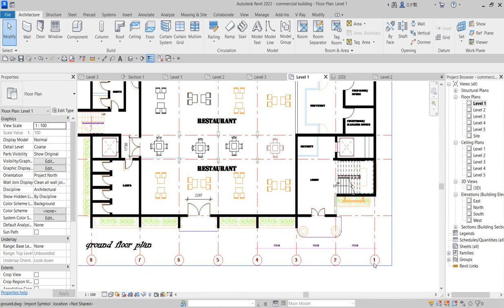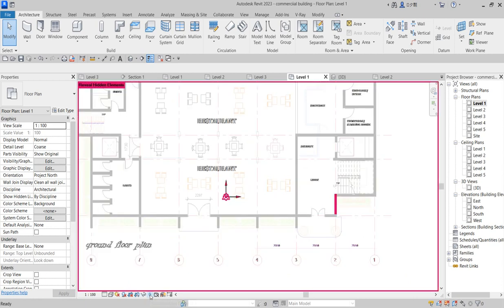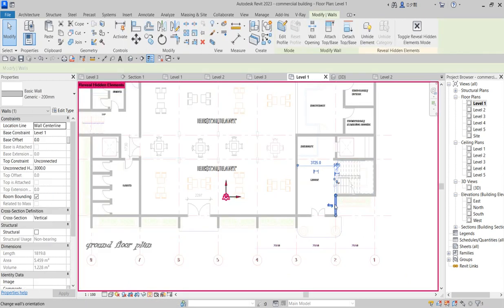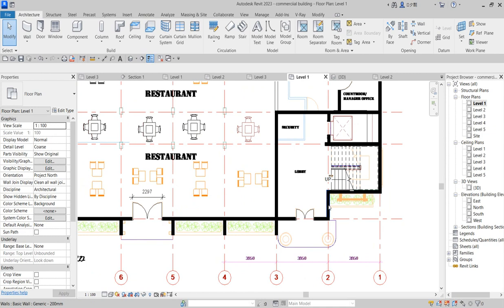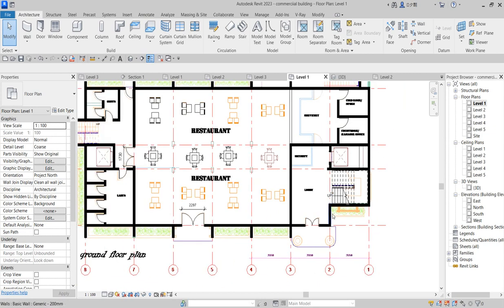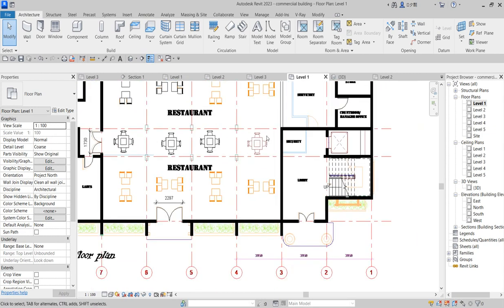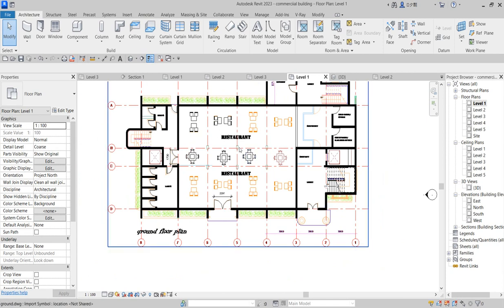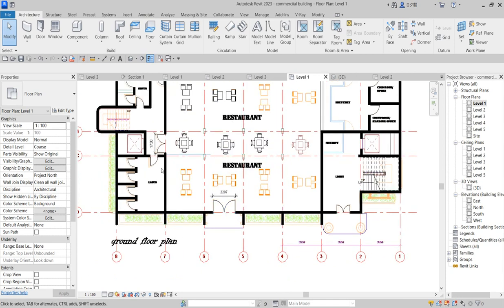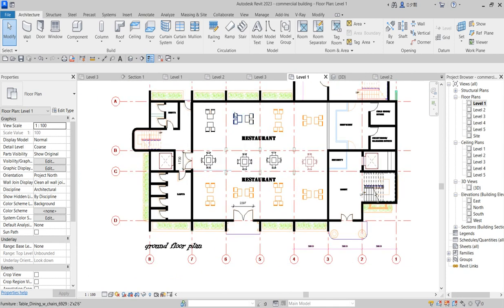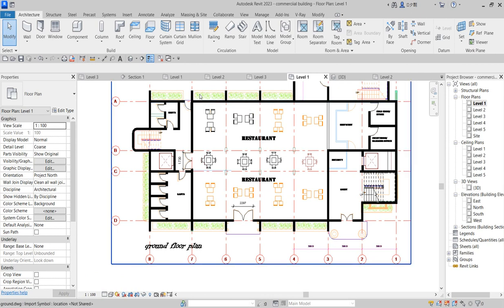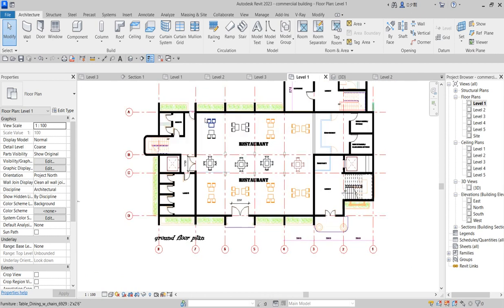So for the part where you have hidden this particular wall, you can bring it back by clicking on reveal hidden elements, then you click on it, then you say unhide the element, so it will come back to normal. Follow suit for the whole walls back. So you do the same thing for any element if you want to hide it and do a little bit of construction under there. So the same way you work on every part of design successfully.